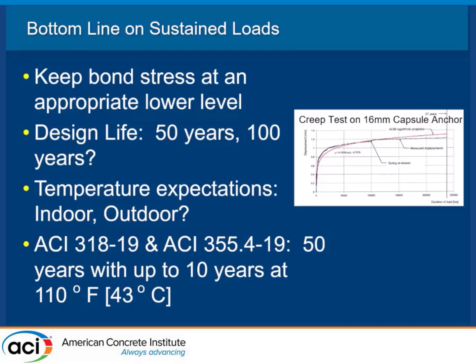And when you get the cut sheet, it'll tell you about that. If you have a sustained load issue, there is a sustained load calc you'll have to make. So if you're under direct tension and you're using epoxy anchors, that information is available, and the manufacturer has to give you that information.